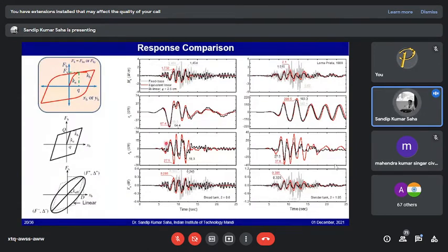Nevertheless, one important observation is the liquid sloshing. As we are making the liquid storage tank more flexible, there is a possibility that the liquid sloshing may get increased, because now the overall structure is flexible. So there could be some resonating phenomenon, in terms of the lower mode, since the sloshing will be in the first mode or so. So it will be excited when the isolation system is in place. So there is a chance that the sloshing displacement in isolated tanks could be more than the sloshing displacement observed in the fixed base tank.